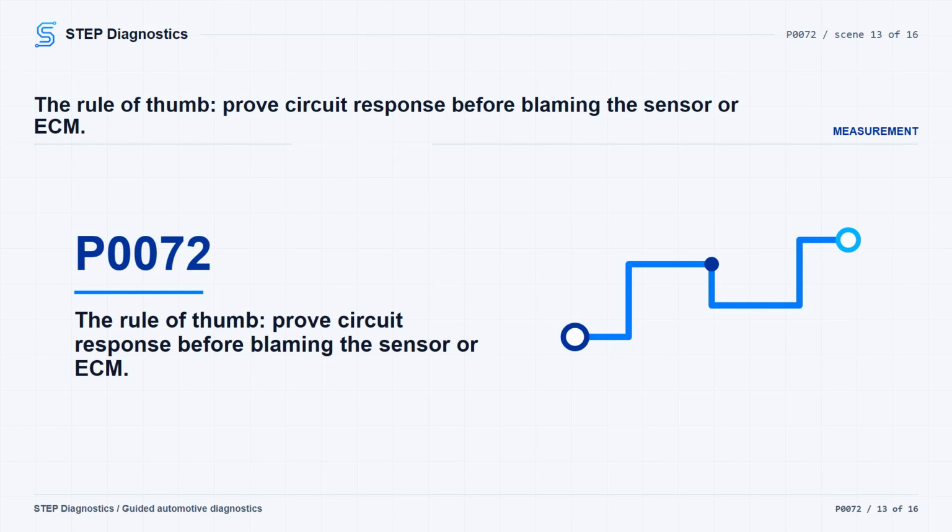If it is less than 1 volt, turn the ignition and vehicle off and test the signal circuit end to end. That circuit should be less than 2 ohms. If it is 2 ohms or greater, repair the open or high resistance. If it is less than 2 ohms, replacement of the K20 engine control module is supported at that point.